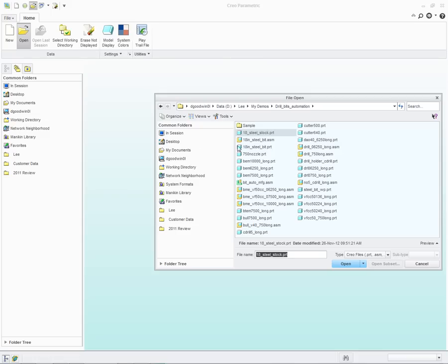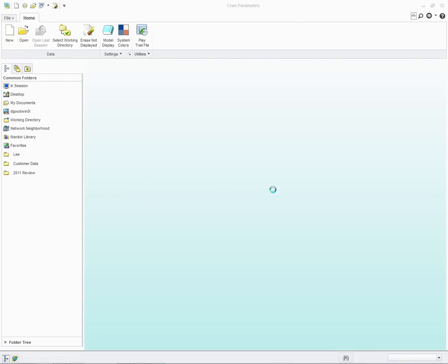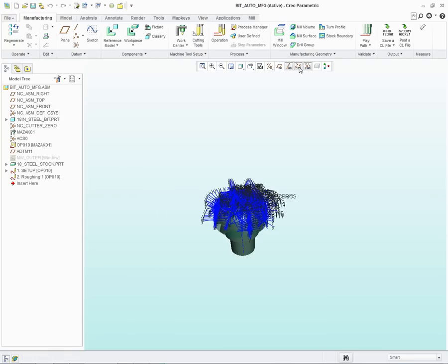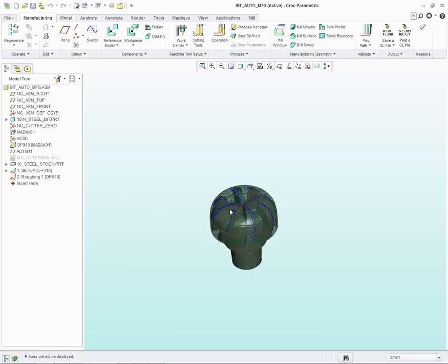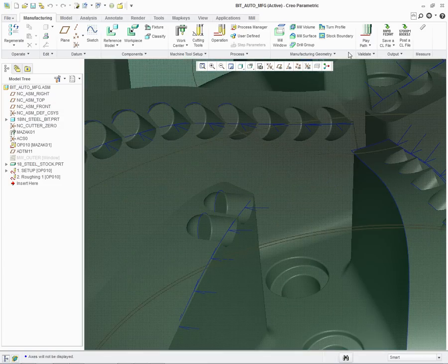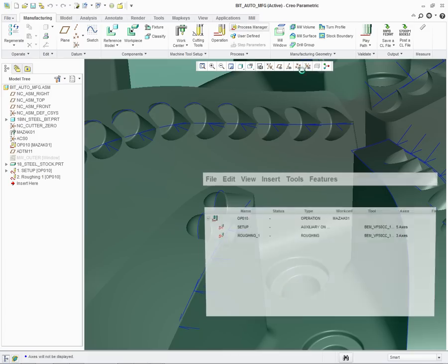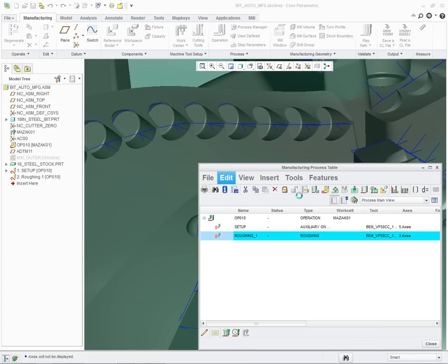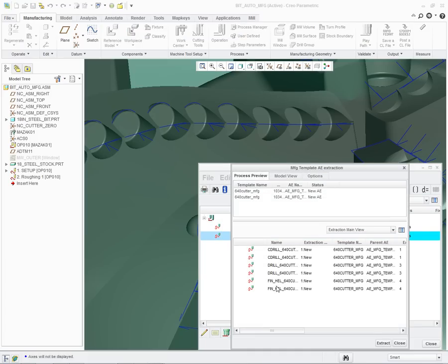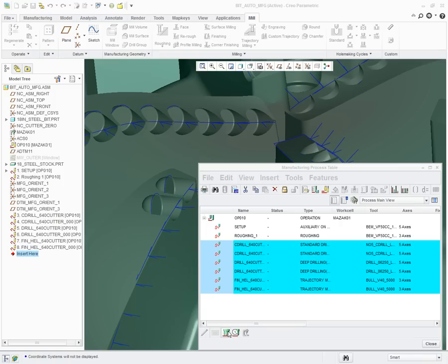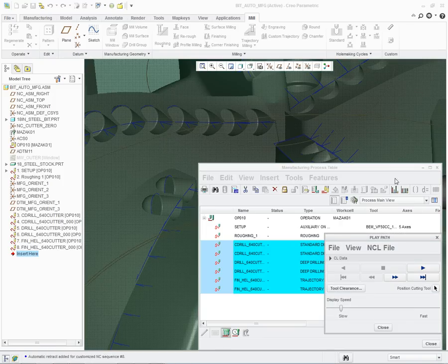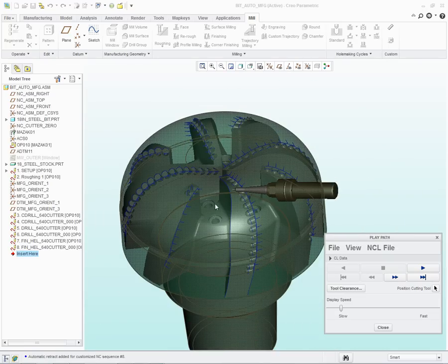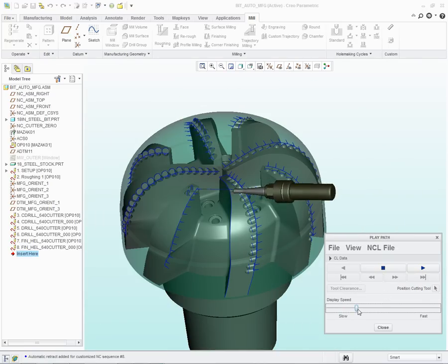notice what we can do. So there are those 2 holes. Again, it knows that embedded inside of here are those 2 annotations that I put in there. All I have to do is, and it's that fast, just say extract, and there's a drill, there's a center drill, there's a ream, whatever you put in. So no extra work on the designer and no extra work in manufacturing, and you absolutely get your part done fast.